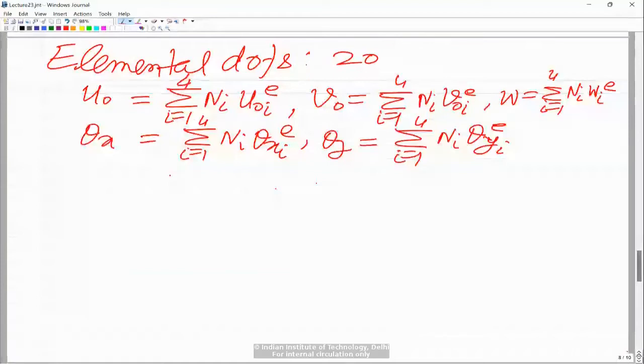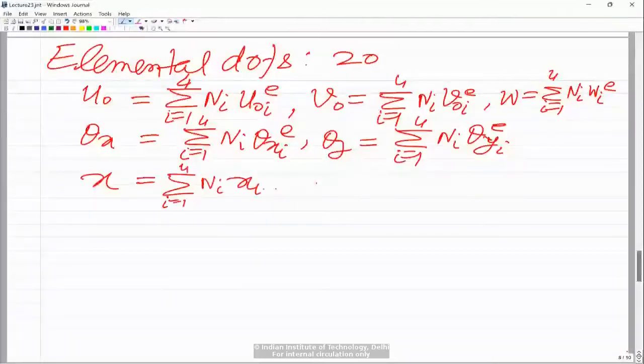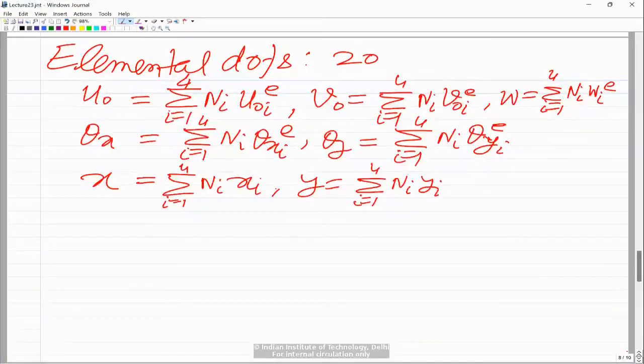You already know, so I'm not writing that. And since it's isoparametric interpolation, we interpolate the x and y coordinates also using the same interpolation function. So x would be summation Ni xi, and y coordinate would be similarly I going from 1 to 4 Ni yi. The only difference is that xi and yi are the known x and y coordinates of an ith node of the element. So this is the interpolation we are actually going to use.